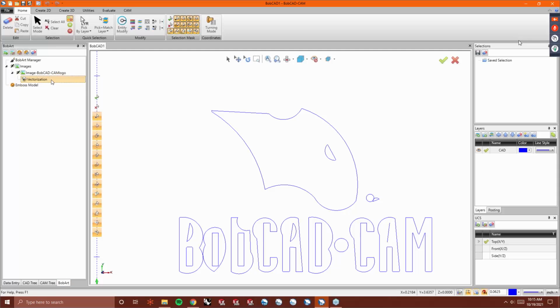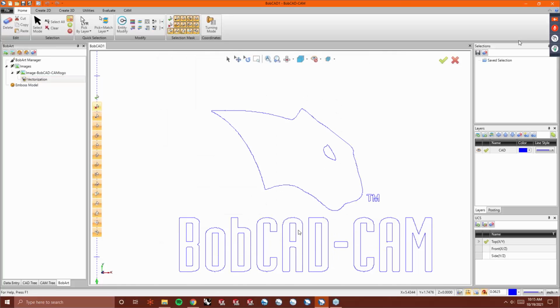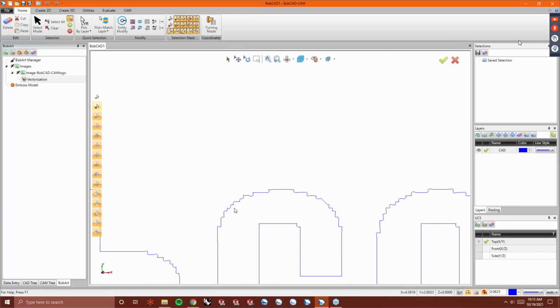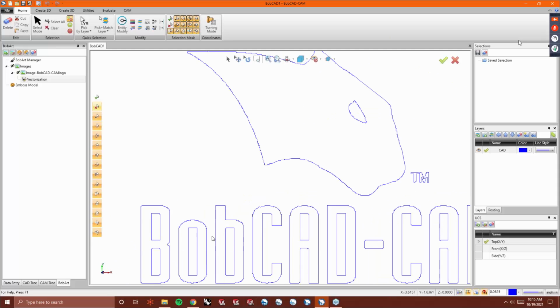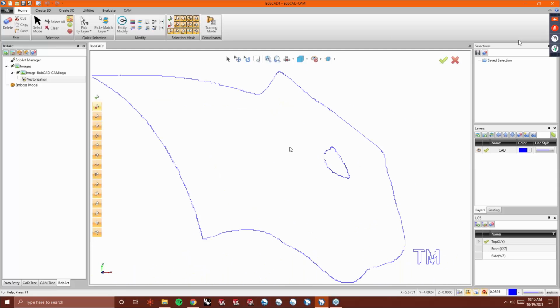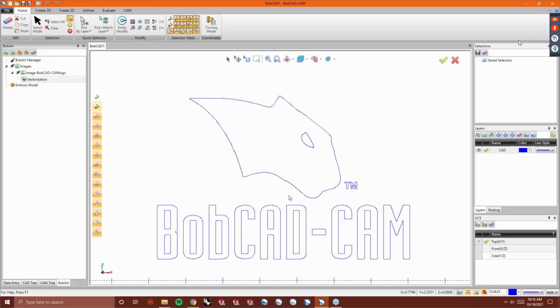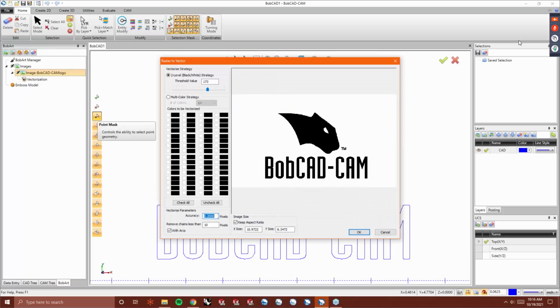If you go too tight, too small of a number, let's say like 0.2, you're going to get a lot more of that jaggedness that's in the pixelization of the image. I'm seeing it all over the place. So there is a fine balance that you want to find when it comes to that accuracy. So let's just jump this up to 1.5.